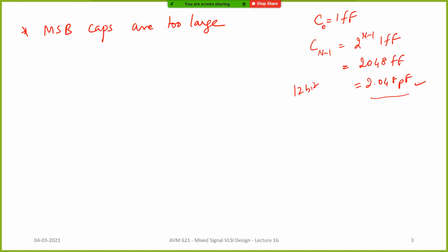High noise. Why will you have high noise? Because of the lesser capacitance, with high fluctuation with the frequency. First of all, a capacitor does not have noise, right? Thermal noise is there only in resistors, correct? So noise is not present in capacitors. Of course, it will have some parasitic resistance, but that's quite negligible. I mean, it's a small value.